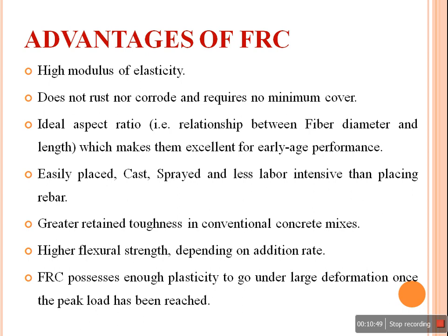So what are the advantages of fiber reinforced concrete? You have high modulus of elasticity, these do not rust nor corrode, and this requires no minimum cover. Easily placed, cast, sprayed, less labor service, greater retained toughness in conventional concrete mixes, high flexural strength, high thermal resistance of concrete, high impact strength of concrete, higher ductility of concrete, and fiber reinforced concrete possesses enough plasticity to undergo a large deformation once the peak load has been reached.